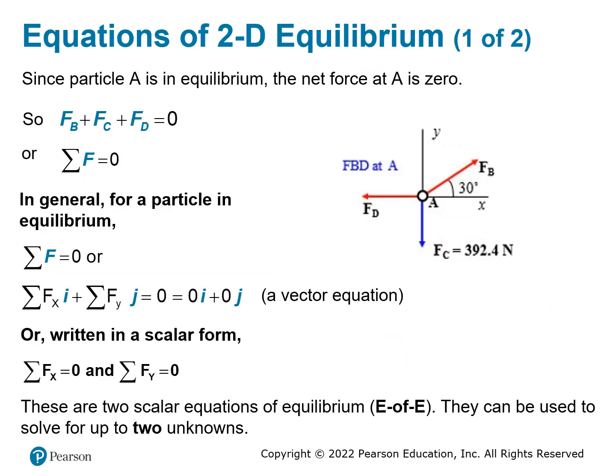Okay. After understanding those, you make a perfect free body diagram. Now we are ready to solve the problem. After you finish the free body diagram, identify all the unknowns in the diagram, and with the information that you can draw from the statement of the question, then you can write the equation of the equilibrium.